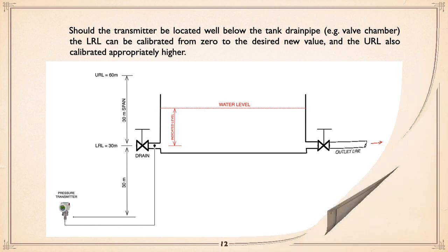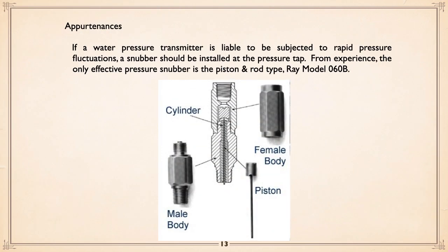Now, for pressure transmitters, one of the things you can have a problem with is dirt in the water, particularly silt. However, you do have to consider that you're going to get large pressure surges in the line. And those pressure surges can be rough on a gauge or pressure transmitter. And of course, you're seeing spikes that you really don't want to see. So you put in a snubber, and because, as I was mentioning, silt in the water is a problem, you want something that will stay reasonably clean.